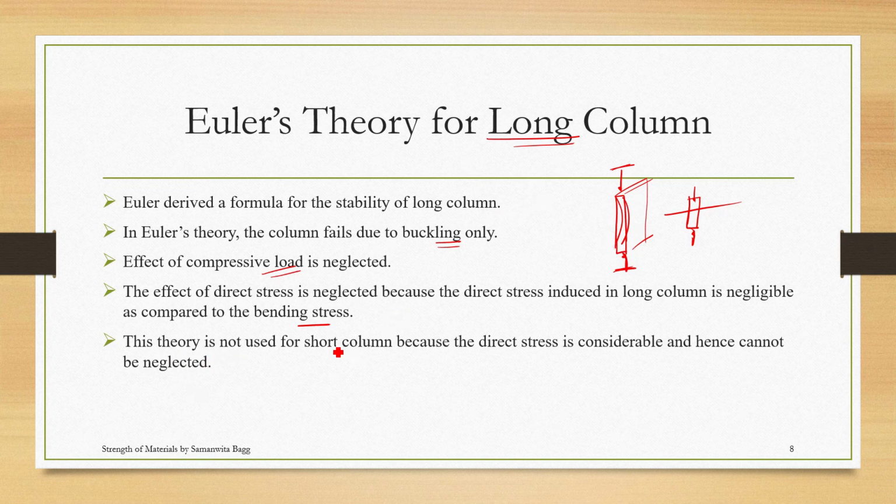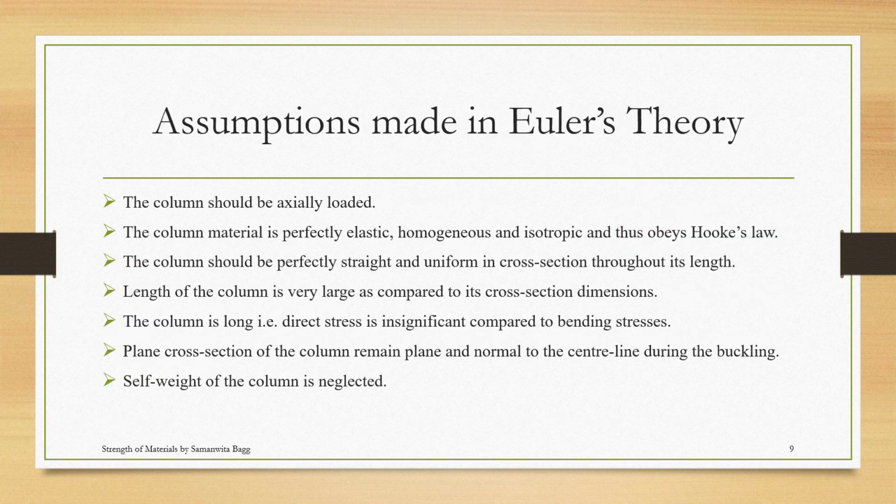This theory is not used for short column because the direct stress is considerable and hence cannot be neglected. When you talk about short column, direct stress comes into picture. And this theory says that direct stress is completely negligible. Hence, you cannot use this theory for short columns.